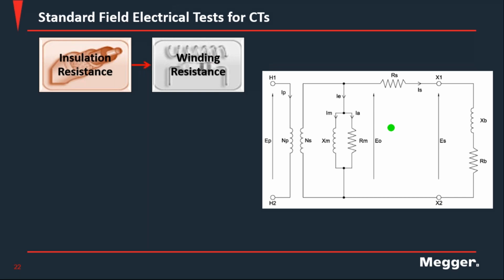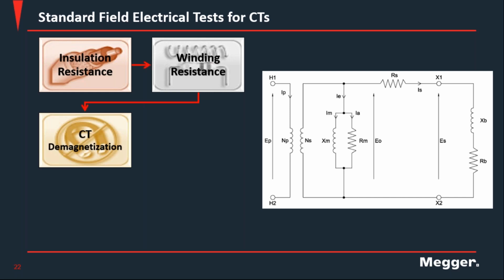And in the process, this DC current that is circulating through the winding is saturating, is magnetizing this branch. The core is being magnetized, and well, if that branch or that core remains in that condition, it will affect the performance of the transformer for the other tests, or for the actual operation of the CT. When you energize, it will probably create inrush current that will cause a trip. So you need to demagnetize the instrument transformer after you run a winding resistance.